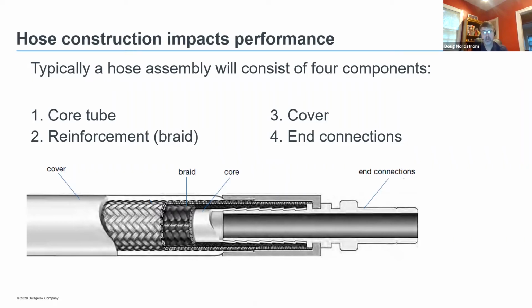We never want a hose end connection to come off the end of the hose because that's a very dangerous failure method. It allows for gross leakage, first of all, and second of all, that full separation can create a whipping effect where the hose is now flying around in the air and can obviously be a very big safety concern. So we always want the actual bulk hose, when overpressurized, to be what bursts. It's a much safer failure mode.